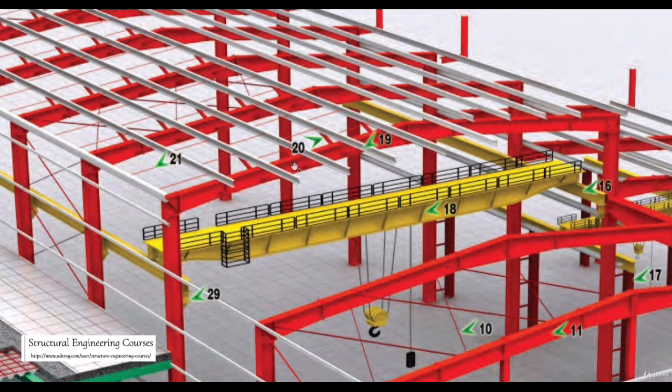So what this flange brace exactly does is that it supports the bottom of the purlin, or it breaks the free length of this purlin, and it makes the Z purlin strong. Second, it also supports the bottom flange of this main rafter here. Basically these rafters are made in I sections. So there are basically two purposes of this flange bracing. One is to support this purlin, and second is to break the free length of the bottom flange of the section. So that is why designers usually assign UNB and UNT parameters in the STAAD software also.